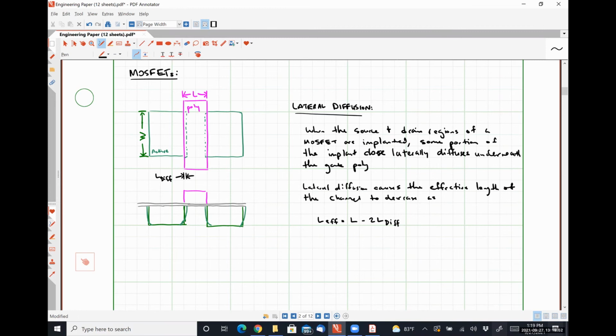So what we've done to this point in the processing is that our polysilicon layer has been deposited on top of our gate oxide, right? We have that very thin layer of gate oxide grown. We deposit polysilicon on top, and then we deposit some more oxide over the surface of everything, and then do a photolithography process to etch away the polysilicon in places that we don't want it, so that we just have our gate left over.